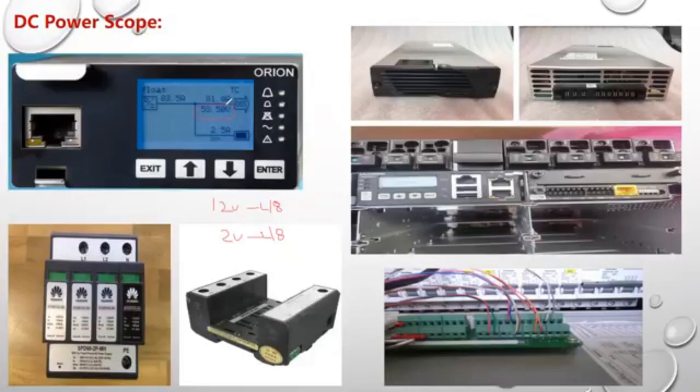Now, if all of your talk is about 48 volt DC, then why is the voltage that appears on the rectifier like 53.5 volts or 54 or 54.5? How did this come? I'm supposed to be actually at 48. I'll tell you simply, the 12 volt battery in case of full charging isn't actually 12 volts.